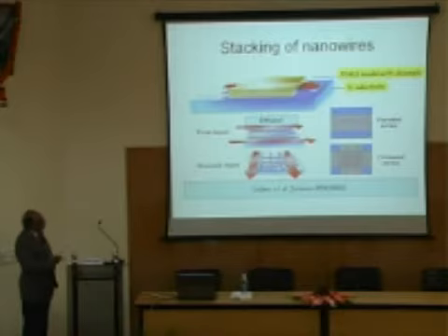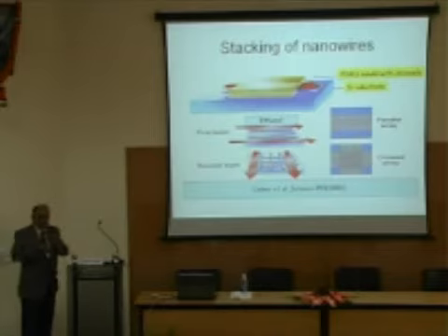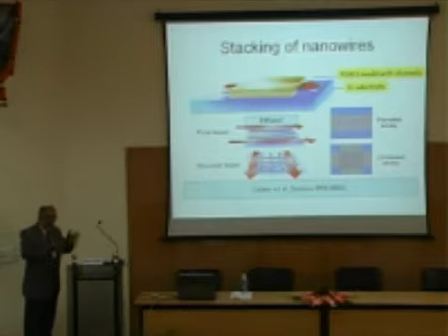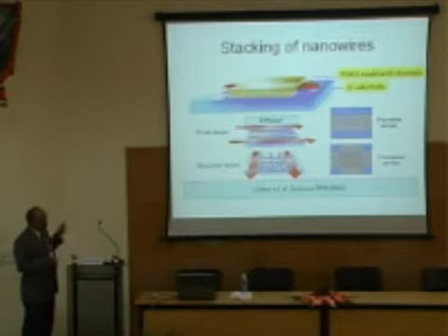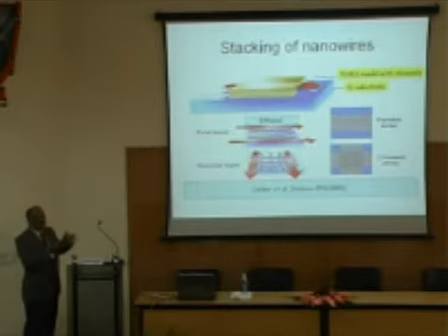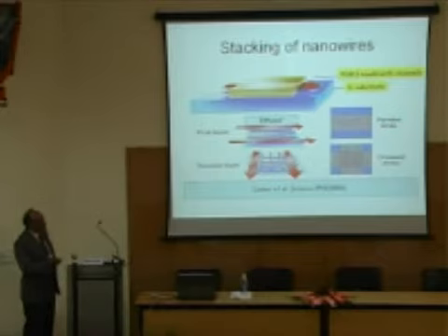Once you make those channels, you put a solution having all your nanowires. Now, there will be millions of nanowires, all in different directions. So, how do you orient them? What he uses is a flux of fluid, and this fluid is ethanol. When the fluid flows, it aligns the nanowires into the channels. So, you get an array of nanowires in the grooves which were already made in the PDMS mold.